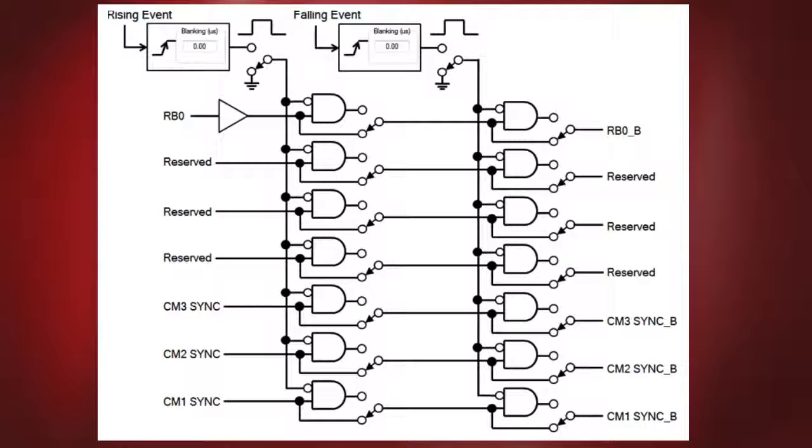The 2 events that signal the output drivers to turn on and off are triggered using the rising and falling events. When a power driver switches from on to off state, or vice versa, it can cause spurious transients in the system that can cause false event triggers if not adequately suppressed. Modulation sources, however, are the only input sources that are not affected by blanking. The blanking time can be entered in the appropriate text box in microseconds, and this is based on the count value calculated from the time base of the PSMC clock chosen earlier.